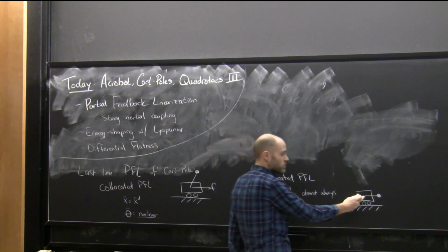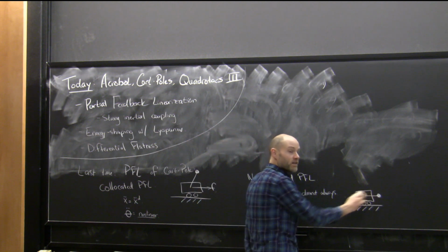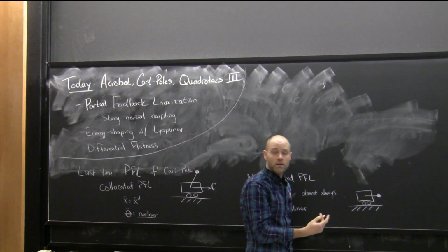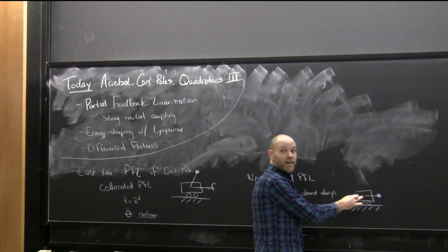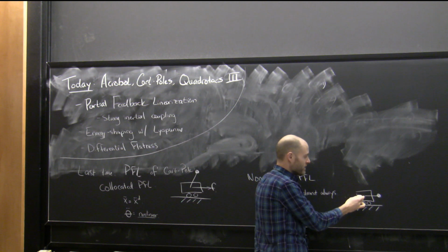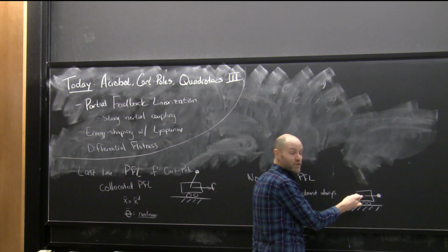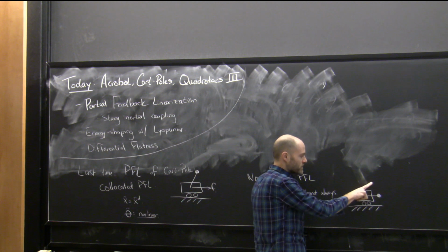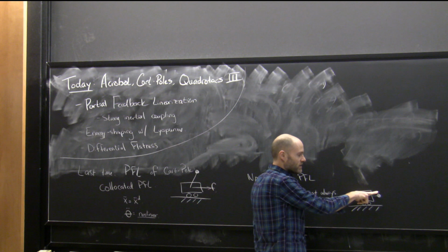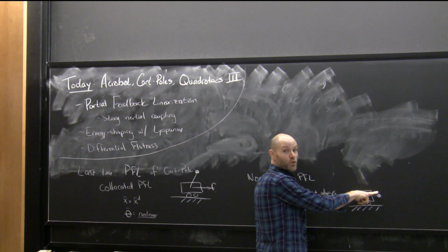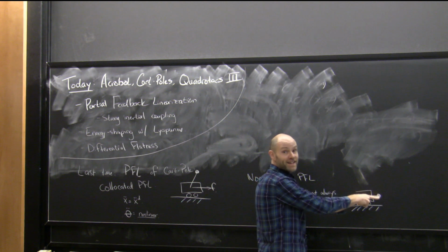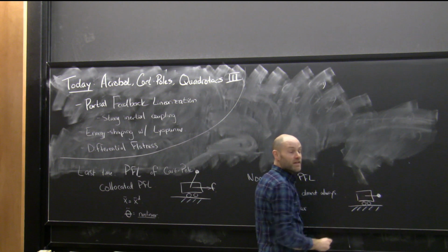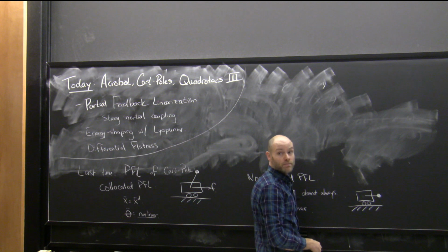This one maybe isn't so tragic. If you let it just wait a second, then it's going to fall down and you can control it again. But a lot of the controllers we choose to write around this have this nasty property, the ones we were tempted to write last time and will finish looking at here. You have to be careful because even if it's not here, maybe it's here. If you write a controller that's trying to control it, the forces you would like to apply in order to stabilize this might go to infinity, as there's a singularity there, and your naive control laws are going to blow up.